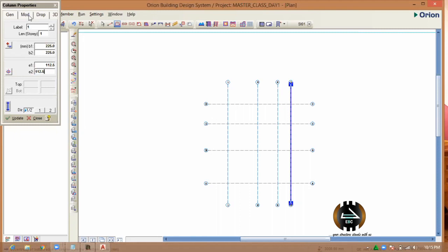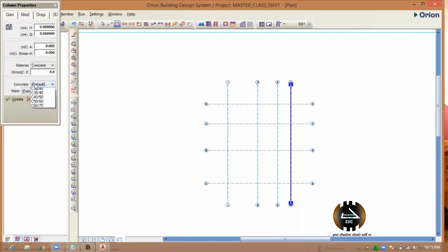So I'll go to model. I'll select default 2025, still 410. You can design, our boss, Onyenoga, used to design with 410. You know, with the situation of things in Nigeria now, the Nigerian factor in steel, I was doing a steel test a few days ago, and I found out that what would be called 410, what I was getting was 300.